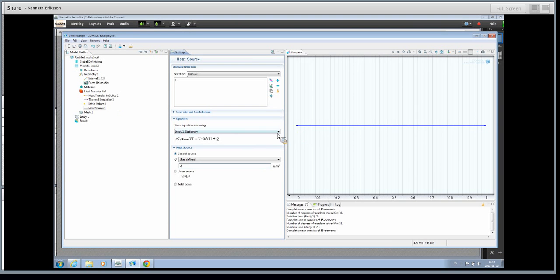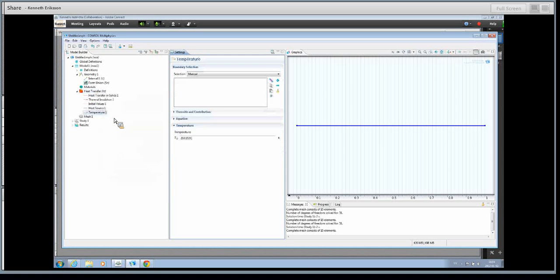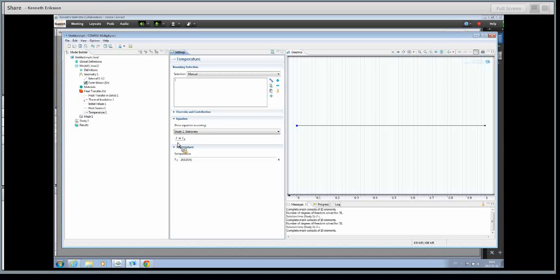To do that, we have to add this possibility by right-clicking again here and going down to the boundary information. And I have some information about the temperature at least part of the boundary, so I press this one. And where does this apply? Well, I mark this part of the boundary, the leftmost boundary point. I add this to my selection, and here is the type of boundary condition that I now have. The temperature is T0, and here I can specify the desired value of T0, and in our case that was 0.